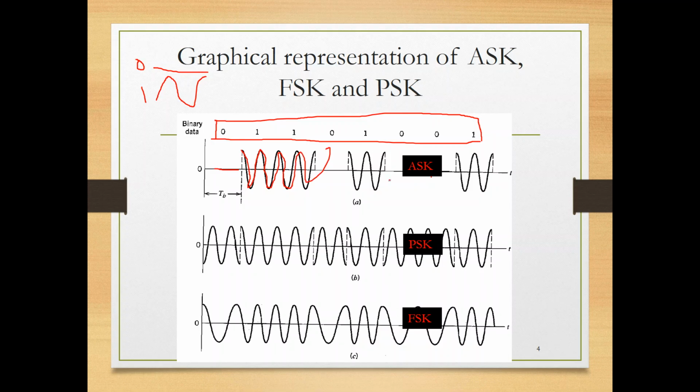Clear? Now I tell you no, I want to change. Amplitude modulation is not good because the channel has too much interference. It has too much noise, and amplitude modulation is not performing well. What do I do? I say, why don't I send it in phase? So in phase, I say if 0 comes, then send with phase minus pi over 2. You start from bottom to up. If 1 comes, you start from top to bottom. So this is phase plus pi over 2,